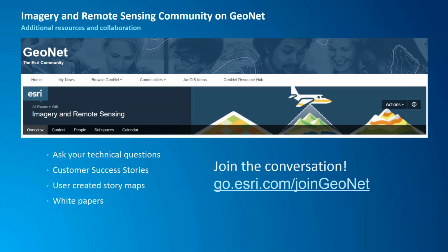There is a question with regards to whether these tools are for processed LiDAR data. I think probably the best way to answer that is the tools are for LAS files. So if you're working with native raw returns from a sensor that haven't been processed into a LAS, they're not going to work. They're specifically designed to work with LAS files. And there are different levels of processing that go into those LAS files.